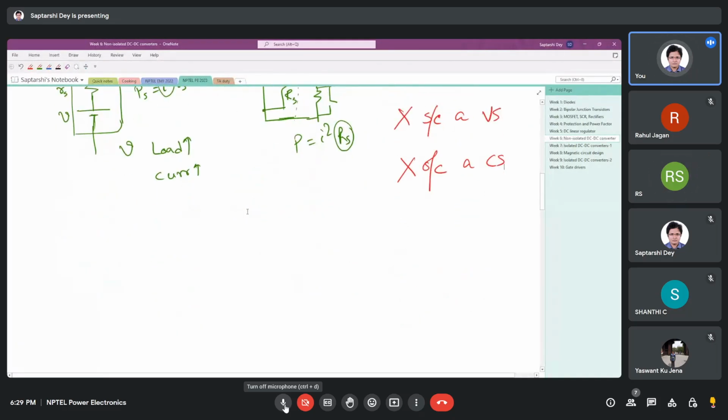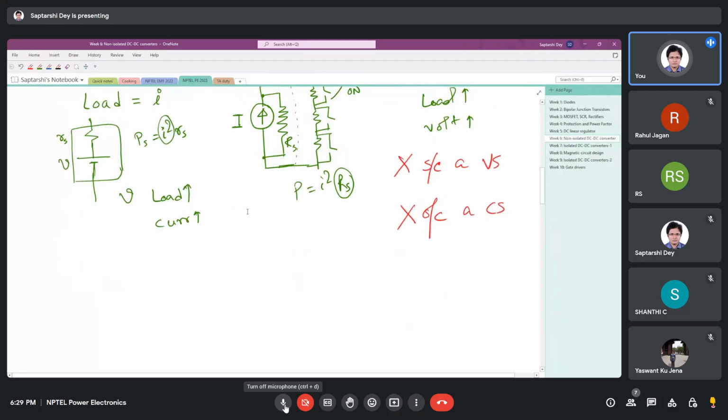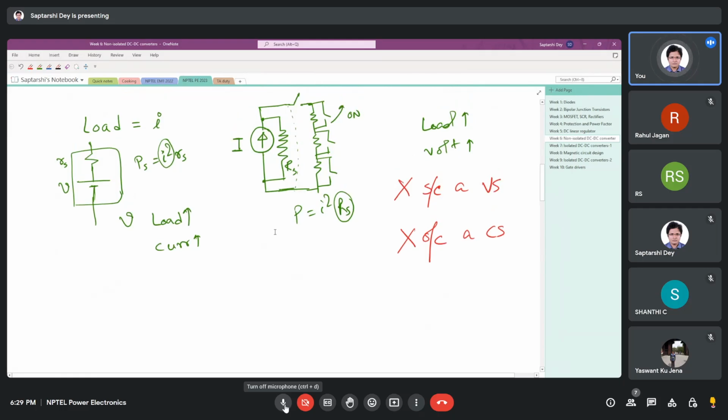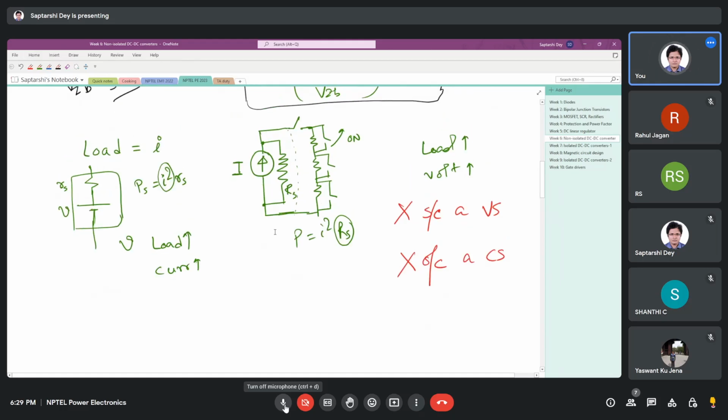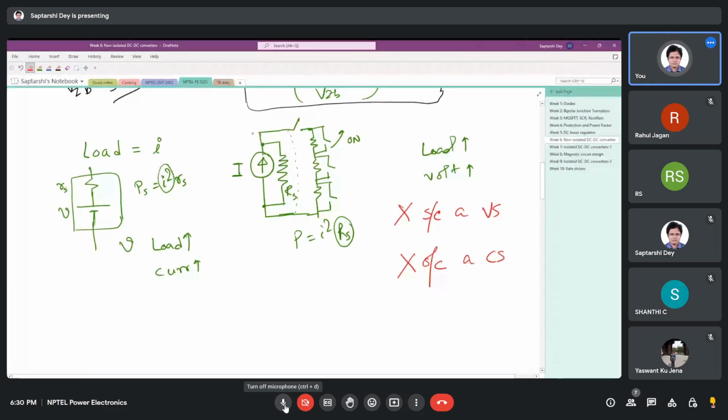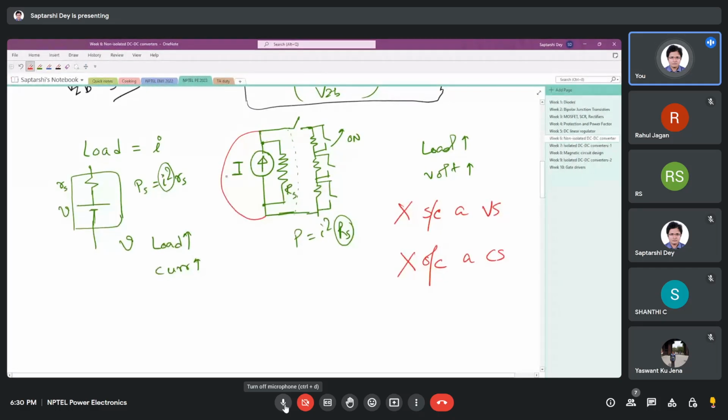So we live in a world of voltage sources. So all our MCBs are made such that if there is a short circuit, it will trip. Had this been a world of current sources, our MCBs would have been like that: if there is an open circuit, it will trip. Trip means it will short circuit the source. If you short circuit the source, the whole current is flowing through the short circuit path, so power loss is zero. For a current source, MCB should be shorting.